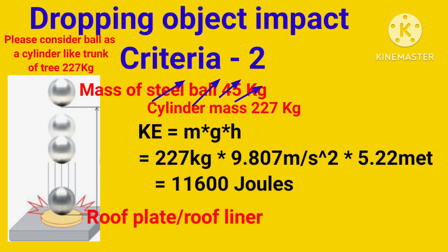It should impact the roof plate, and from the deviation point of view, how can we clear that result? If the impact of the sphere is entirely within a 100 mm radius, then only can we say that yes, our FOPS level 1 test is passed.